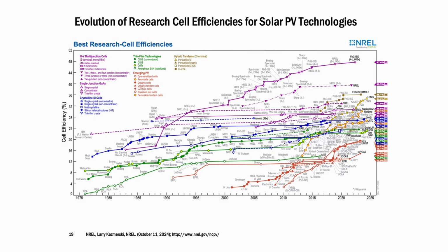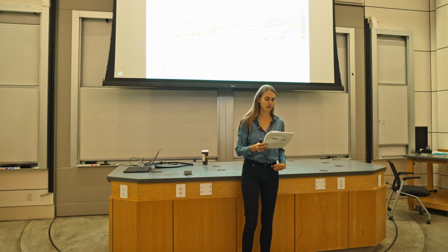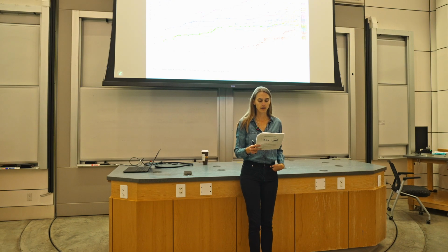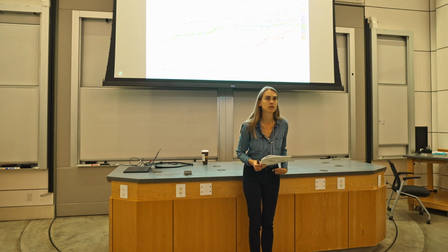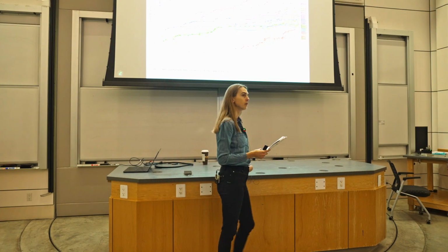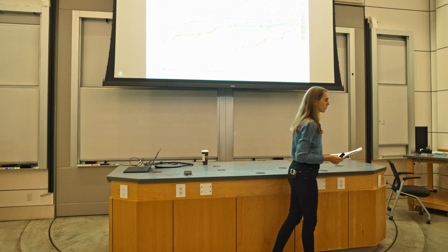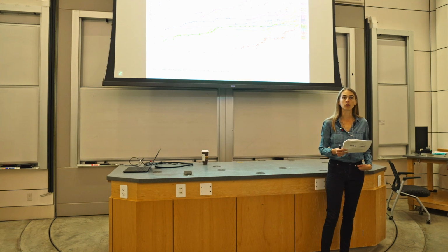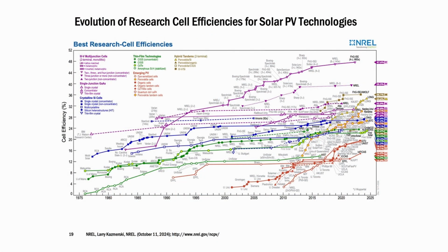And then you've got cadmium telluride in green, the main one with the yellow fill up there, that has about 23% max efficiency that we've seen in the lab. It's only slightly less efficient than silicon cells, but has achieved faster efficiency gains in just the last decade. The max theoretical efficiency for a single junction solar cell is 33.7%. But we can see in this chart that a lot of the solar cells have achieved efficiencies higher than that, and those are the ones in purple.